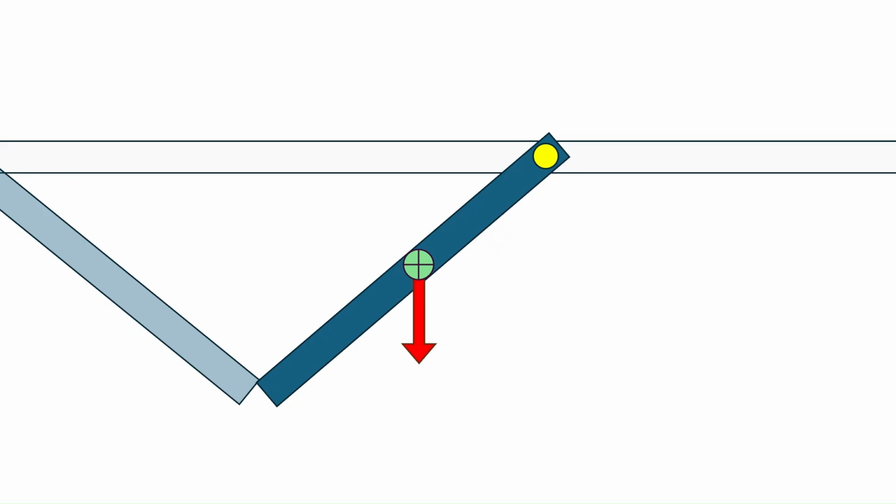diagram. Then, because the right side of the panel is supported by that wheel, the normal force is applied in the upward direction at that point. We have the horizontal force of whatever mechanism is causing the movement, and at the other end, at the joint with the previous panel, a tension force pulls it both outward and upward at whatever is the angle of that panel. Now think about how these forces affect rotational movement. When a force is applied to an object that can freely rotate about an axis, that is called torque.